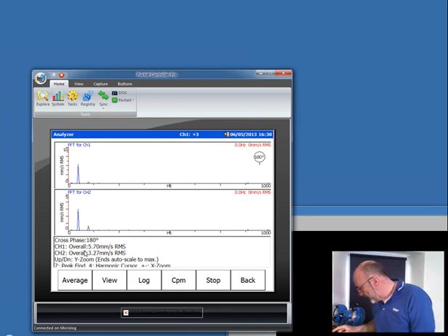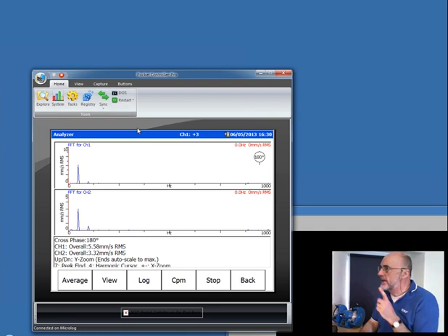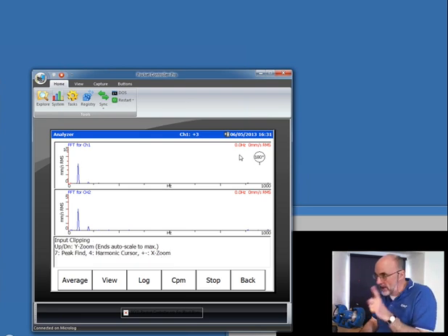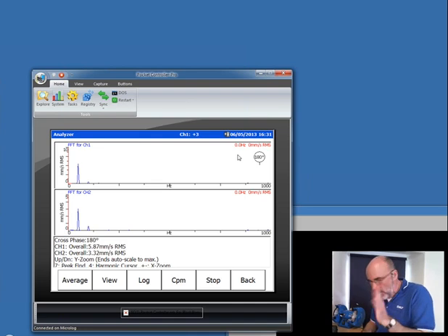If I put my cursor on the running speed, and here's a tip, by the way, you'll notice that the circle with the tick mark is saying 180 degrees. Now, a trap that you can fall into is that's the phase at the cursor position. So what you need to do is put the cursor onto the running speed, and the quickest way you can do that is press the 7 key.